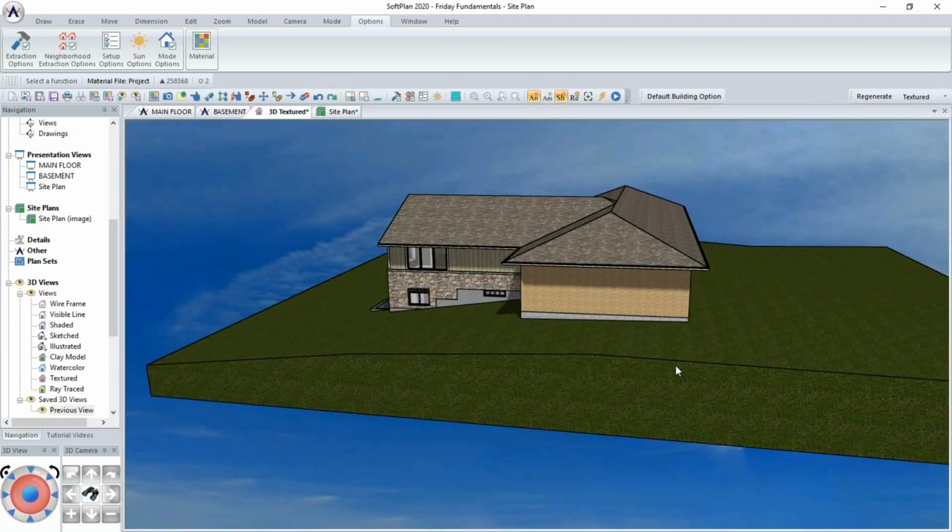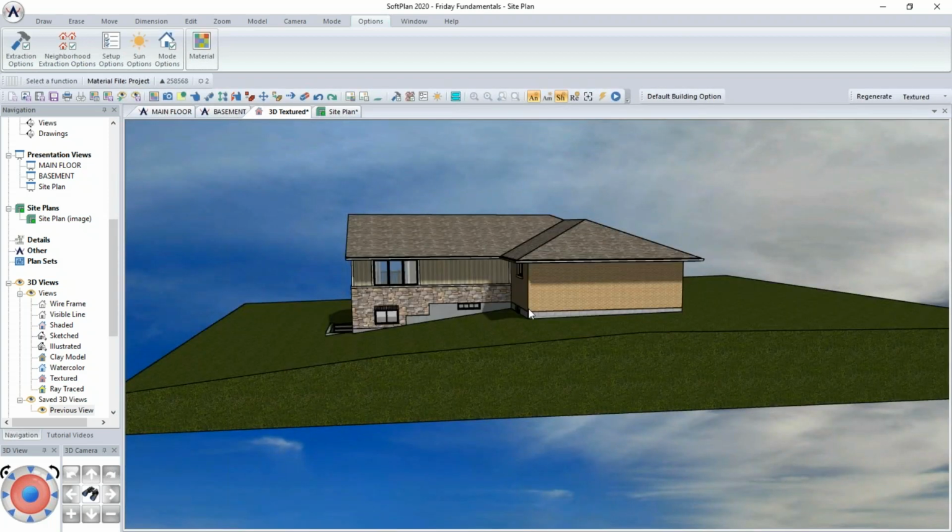So to quickly slope your site, once you have your building outline and your property established, you start editing corners of your building outline and the site so you can establish what the elevation is at those corners. Next thing we're going to do, because we add towards the existing structure here, the actual slope is a little different between where the original building is and where the end of the new building.